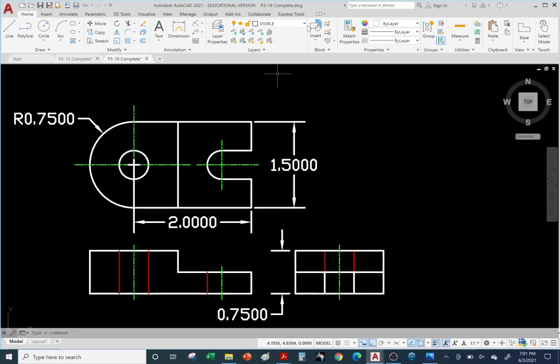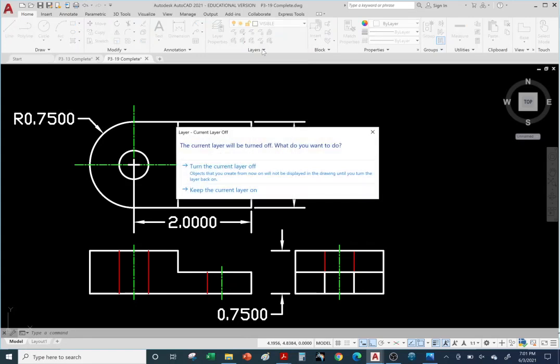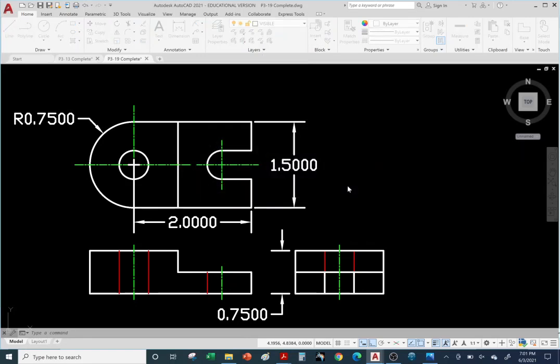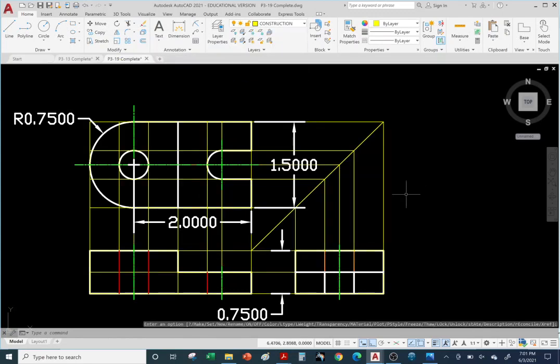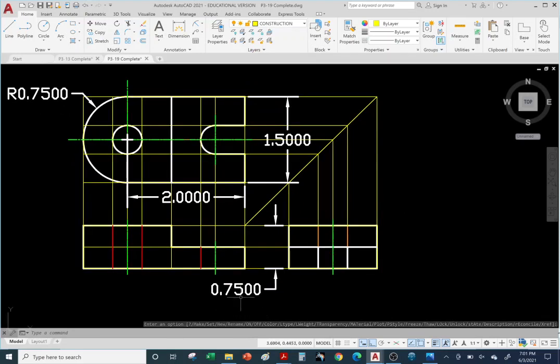All right, so let's go over to our construction layer, and let's start by drawing our box. Okay, so our box will be 0.75 in height, 1.5 in depth. This would be also in parentheses because that's double dimensioning with the 0.75. And the overall length is 2.75.